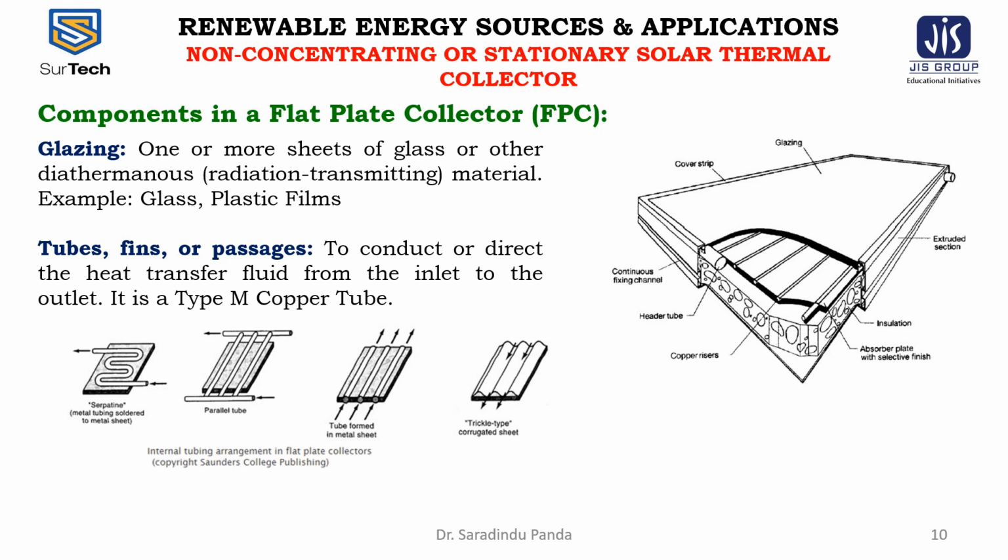Glass with low iron content has a relatively high transmittance for solar radiation, approximately 0.85 to 0.90 at normal incidence, but its transmittance is essentially 0 for the long wave thermal radiation, that is 5 to 50 micrometers, emitted by the sun heated surface.